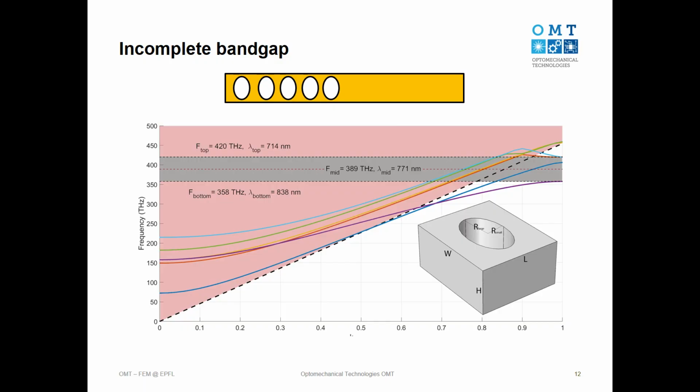So coming back to this picture, I want to recall once that when we want to make an optical simulation for periodic structures, we have to take care of the post-processing of our data. Here doesn't mean that the light is propagating because of this light cone, that is the dispersion of the light in the free space. So whatever is here has the n effective smaller than 1, so it cannot propagate.